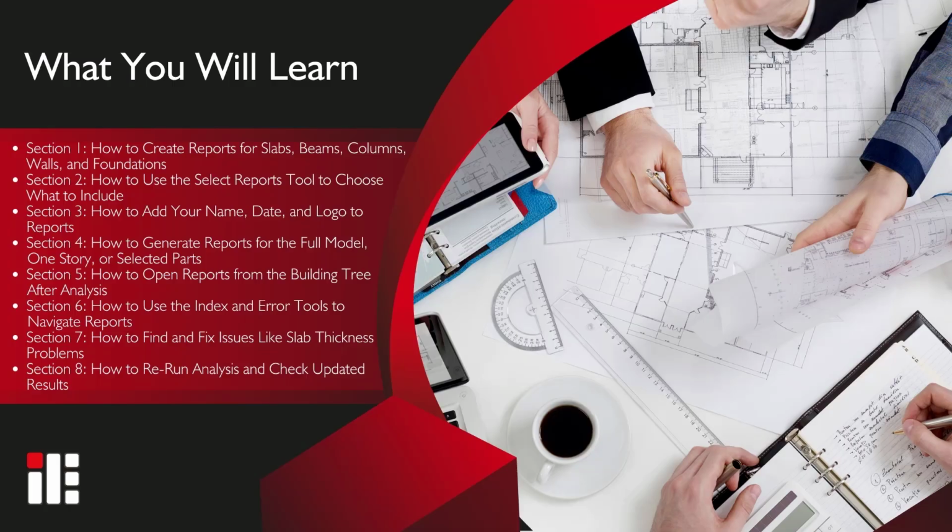In this video, you'll learn how to generate detailed reports for slabs, beams, columns, and walls in ideCAD Structural. You'll see how to use the Select Reports tool to include exactly what you need, and customize the reports with your name, date, and company logo. We'll show you how to create reports for the whole project, a single story, or just selected elements.